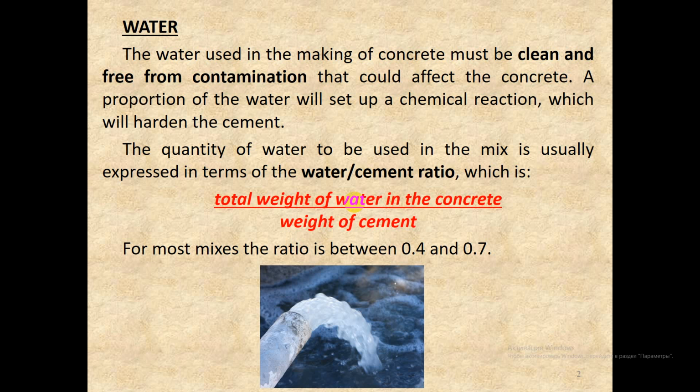This water either remains trapped in the concrete matrix after the concrete has hardened or evaporates, resulting in a degree of permeability being imparted to the mix. Adding too much water increases the permeability, which reduces both concrete strength and durability.